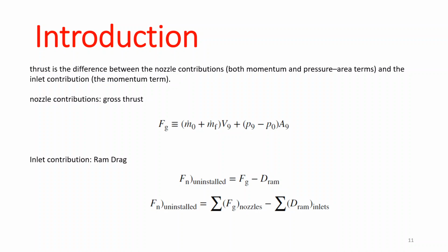Exactly. So the thing is, as I keep mentioning, in thrust calculations, we don't care about the combustors and the compressors and the turbines. We care about the inlet and outlet. As long as you have an inlet and an outlet, you will have thrust generation. It doesn't really matter what is happening there. I mean, what is happening there is going to contribute to the exit condition, of course. But if you already have the exit condition, you can calculate the thrust. So, what are those engines called? Those with the bypass ratio.